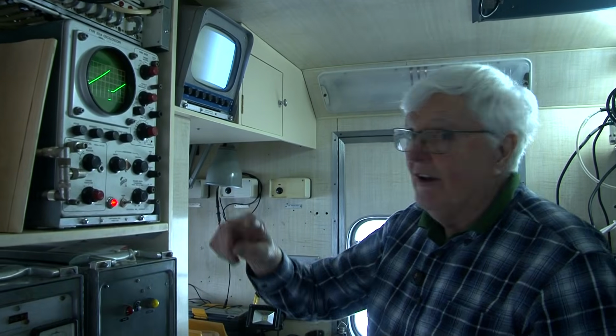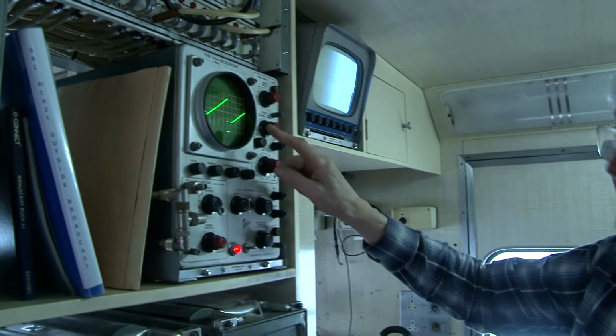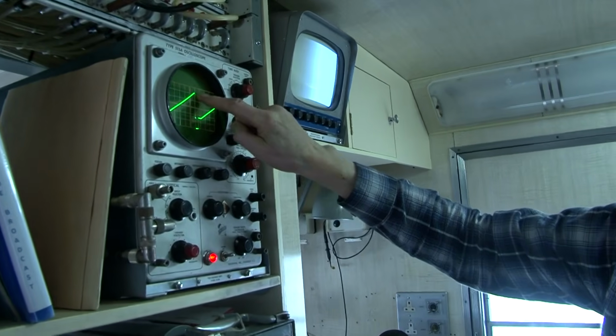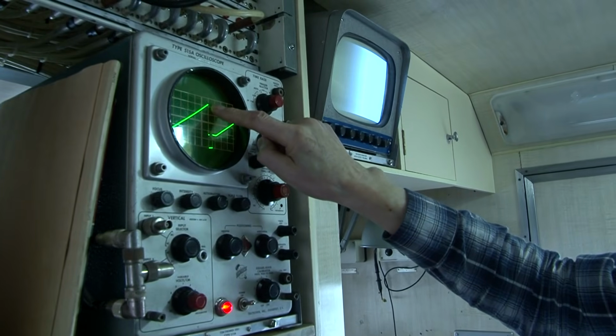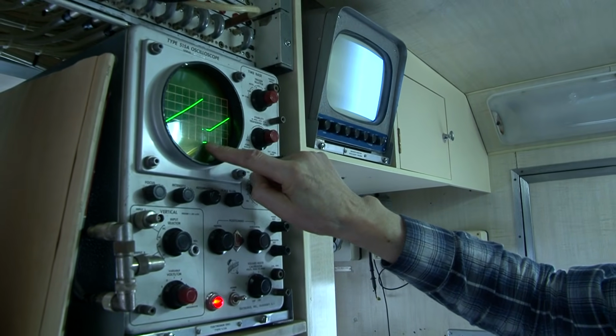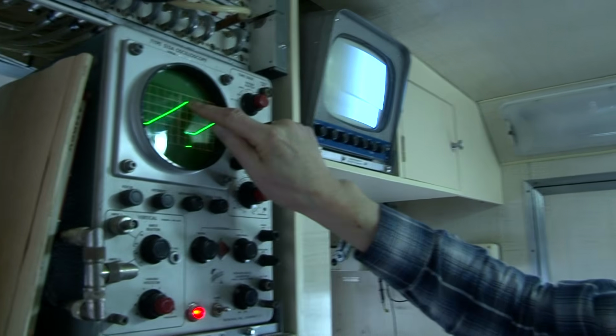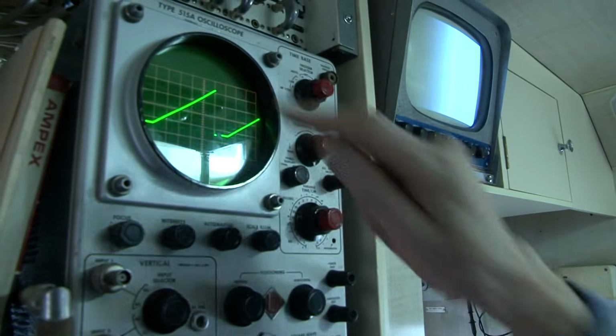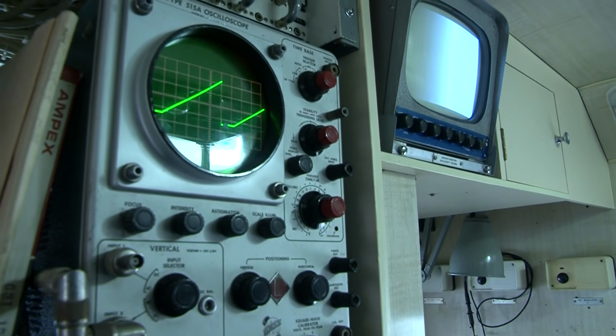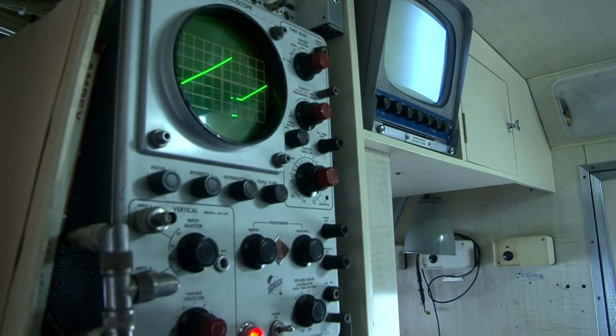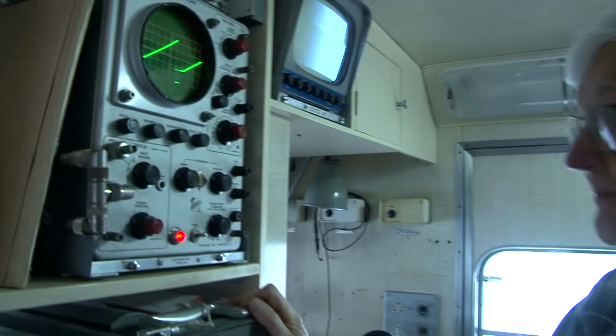And on the scope here, now you can see the peak there, which represents peak white, black level, and the bottom of the sync pulse, and of course the linearity of the rising Sawtooth is an indication that the amplifiers and the circuits that it's passing through are still linear.